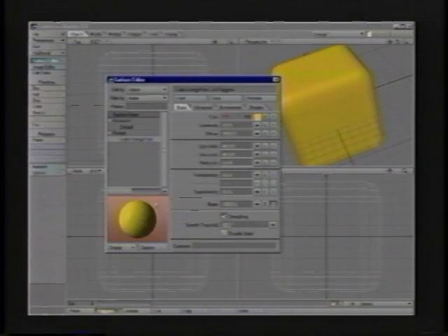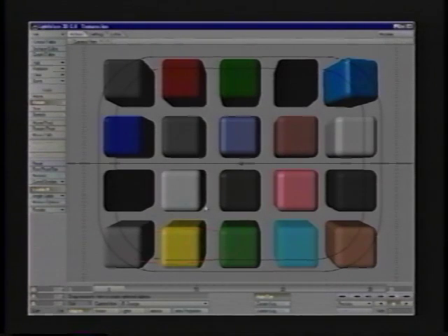One thing I should point out, because Modeler doesn't have a renderer, you won't be able to use Viper inside this window because it needs to trap that render data that it gets from Layout. So for working with Viper, you do need to be in the Layout environment. All right, let's go ahead and jump back over to Layout then. So we've got that environment set.